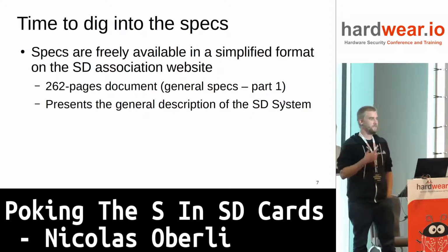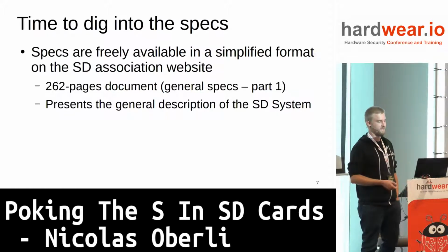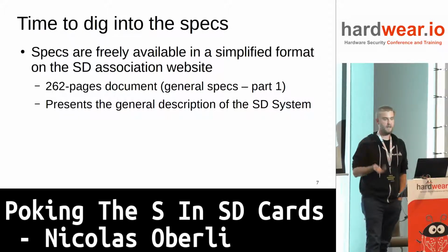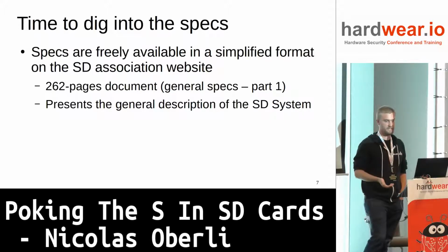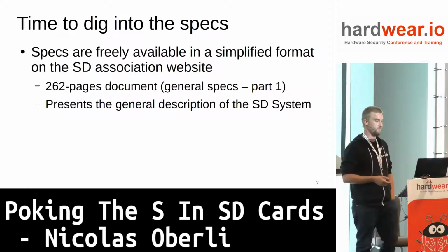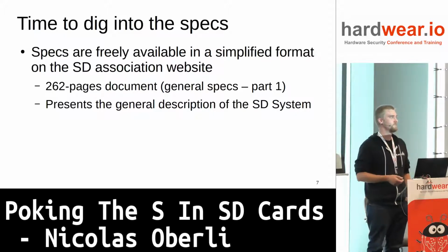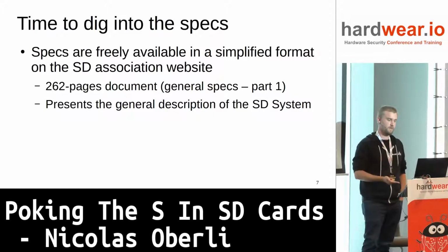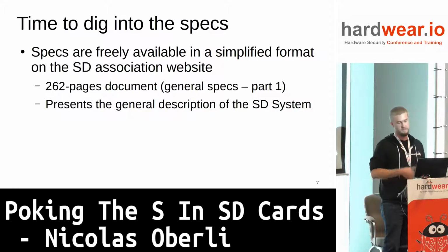If you want to know exactly how it works, the best thing to do is to find documentation and specs. They are available on sdcard.org. You can get what they call the general simplified specs. This is the first part. It's a 260-ish page document with all information about the physical size of the card, how the commands should be sent, what are the responses that you get, etc.